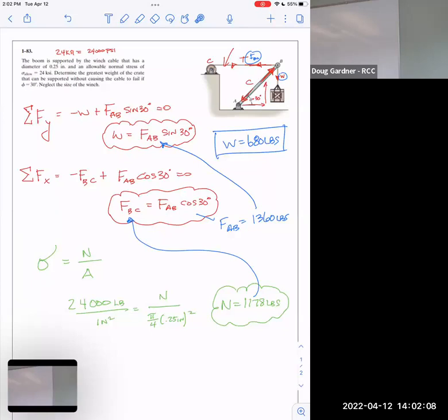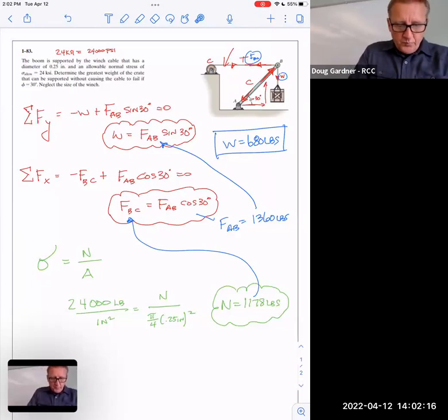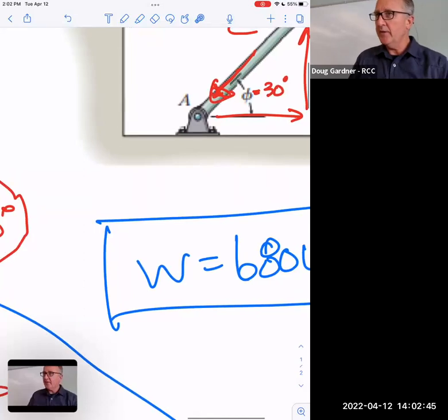And by using the maximum. So you're saying find that maximum weight. At 30 degrees, it could only allow 24 ksi, but that 30 degrees or 24 is going to change as the angle changes. No, the 24 won't, because that's how strong the cable is. But the weight, the 680 that we got for the maximum weight load on it, will change. So we should find a maximum at 90 and then a maximum at 0. Yeah. So as an engineer, either that would be stuck at 30. And notice the way it's drawn, it's meant to pivot. It's not like it's welded in that position.